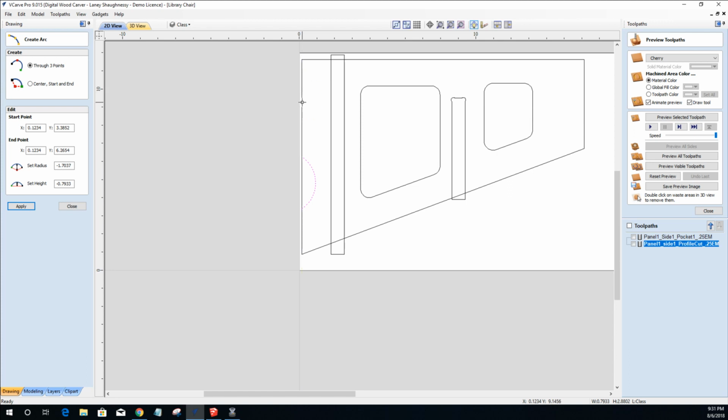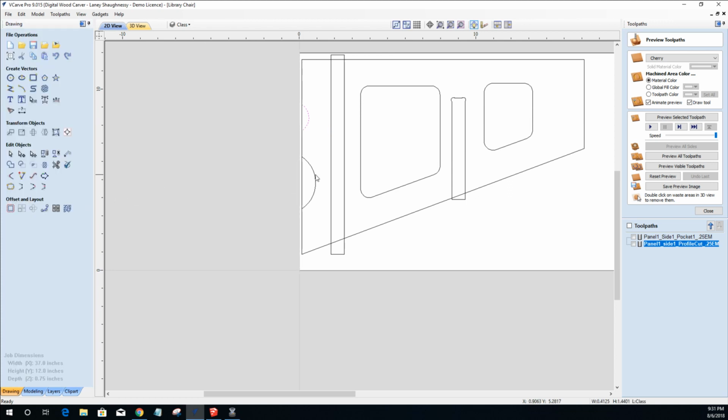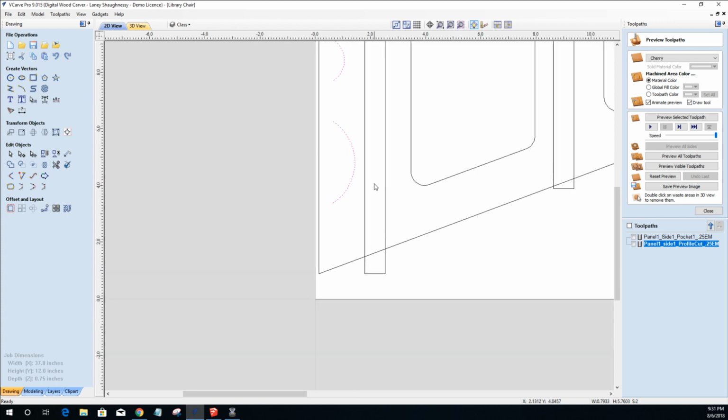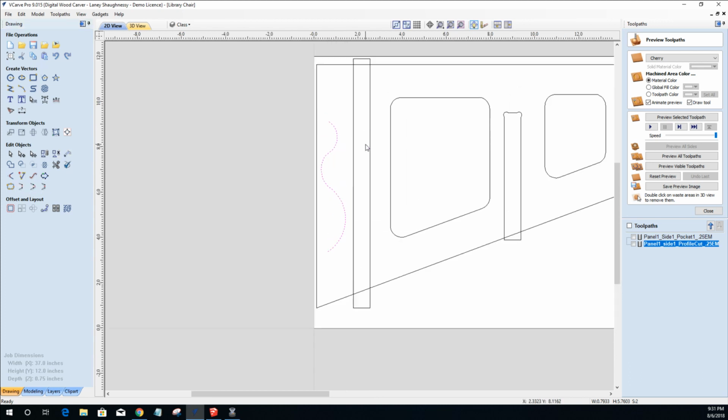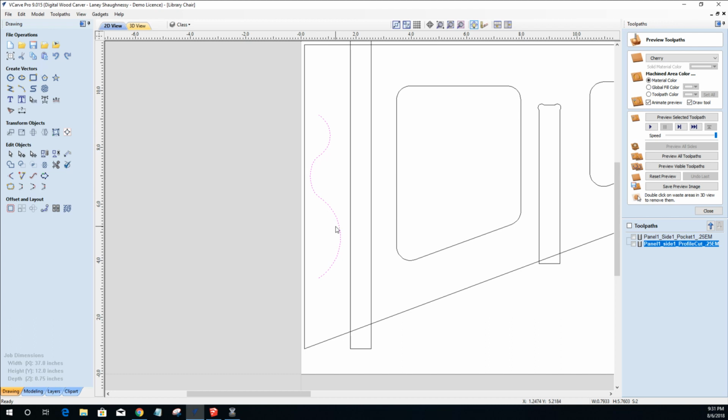That's my center right there. Click, and I'm going to go to the center point there and pull this up. Not as much. And then while I've done that, what I'm going to do is I'm going to take both of these and I'm going to move them up, leaving enough meat between the top of this arc and my spline, right? And then I'm going to take these two guys right here and I'm going to join them with a smooth curve to create that transition there.